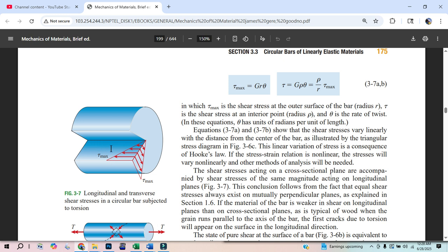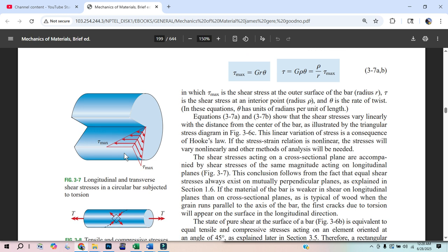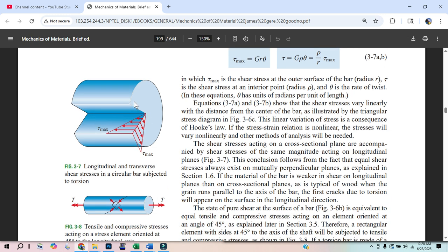And once I know this shear is 22,000, I know what my thing is made out of, I don't know the torque. So I twist something, I look at the angle, and I want to know the torque. I twisted it, know the angle, I know the circumferential distance. So now we know that's a small angle, and radians times radius is that circumferential distance.